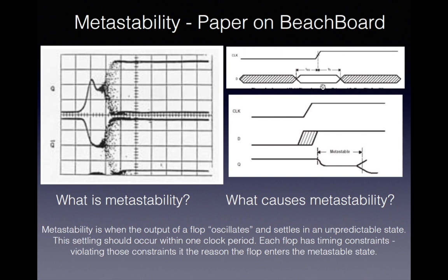What's exactly going on is subject to debate. It may not be oscillating. They say it floats between active states. Whatever. It's a period of time when the output is not usable. That is the metastable state. That is what we want to stay away from. And what we assert is that if a flop does reach a metastable state, it will settle. By settle, I mean it will either end up as a 0 or 1 in less than 1 clock period.